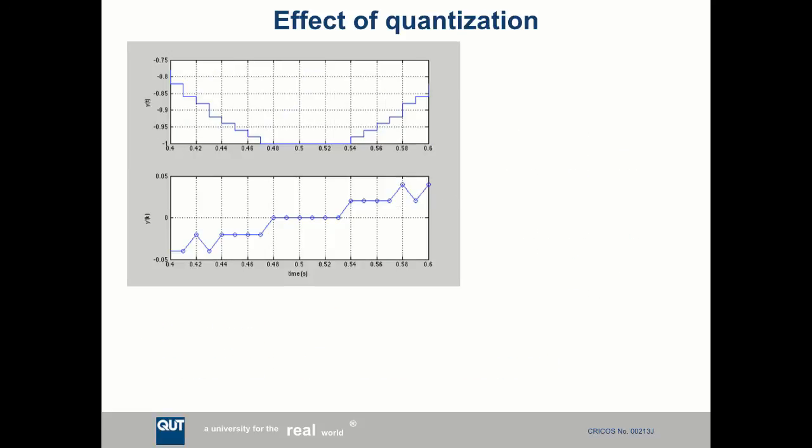If we zoom in on it, we can sort of see what's going on. I've zoomed in on one of the flat bits at the bottom of the input wave. And you can see that the quantization has made it flat for quite a long time. So if I compute the derivative across the flat bit, of course it's going to be 0. Right? For quite a long time, the output is 0. Right? And then it kicks up a notch, and it has got a particular value for a little while, and so on. So it's the quantization that is causing this bad effect.